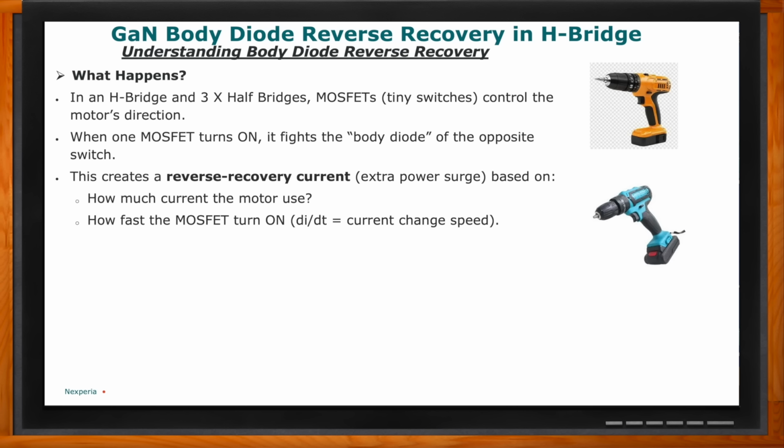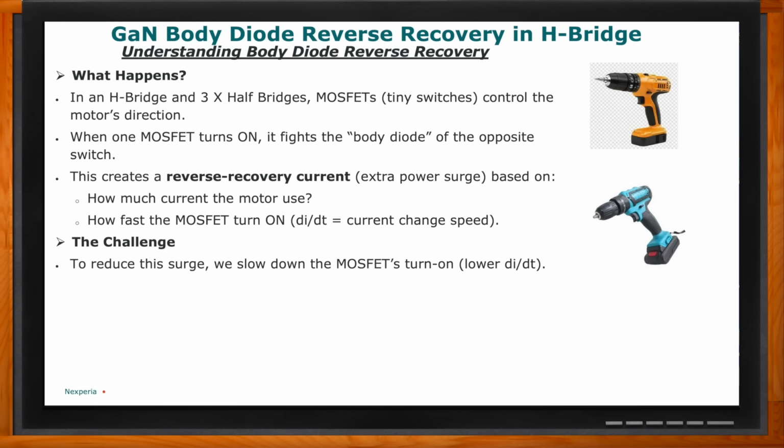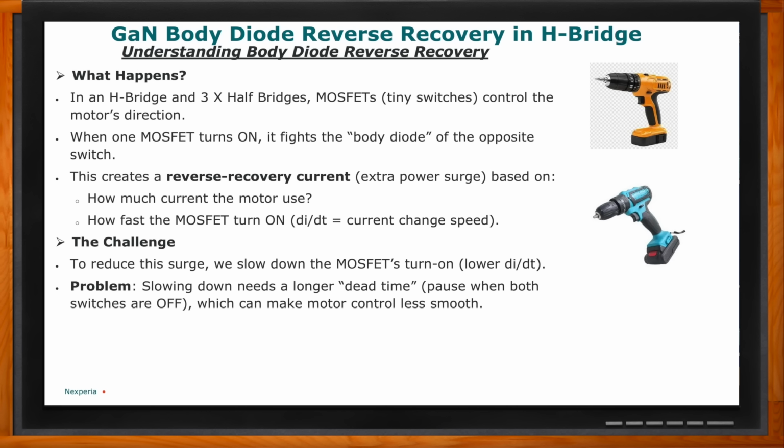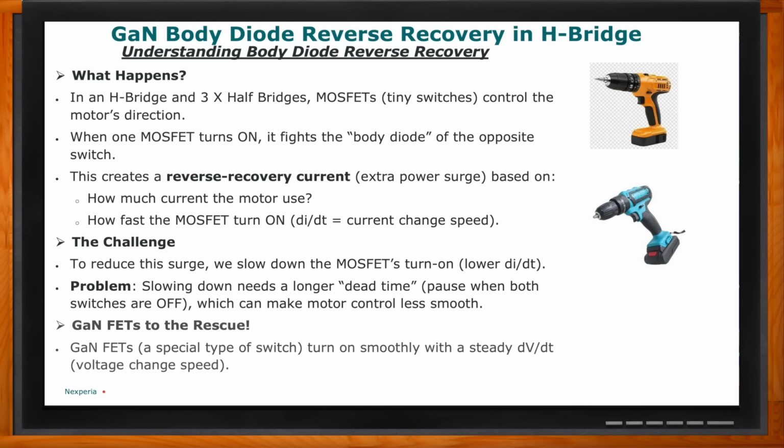So when the one MOSFET, usually at the top, turns on, the other one has to turn off, or vice versa. That becomes a problem because if the MOSFET that has to be turned off is slower than the MOSFET that is being turned on, then we have a problem, because all that energy will circulate and it becomes a lot less efficient overall.